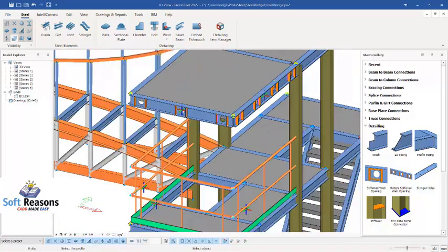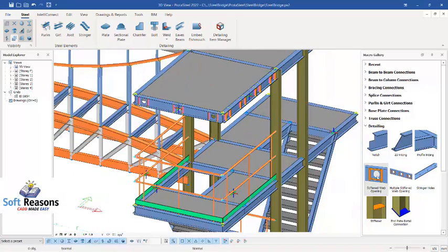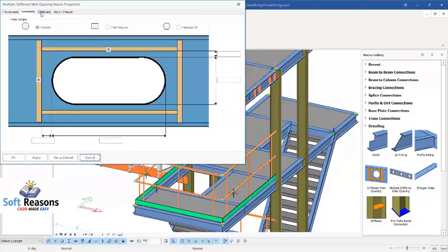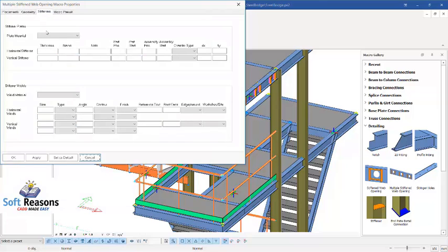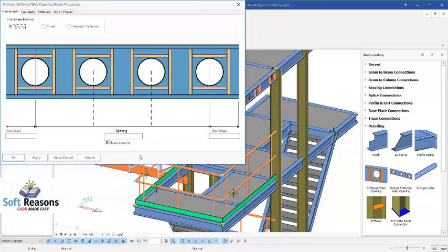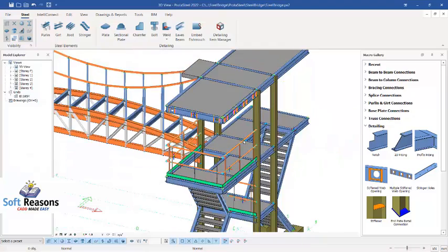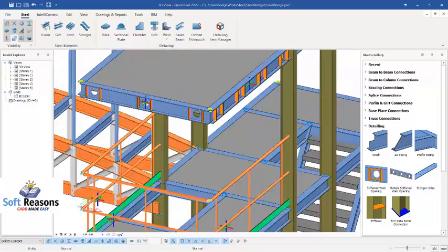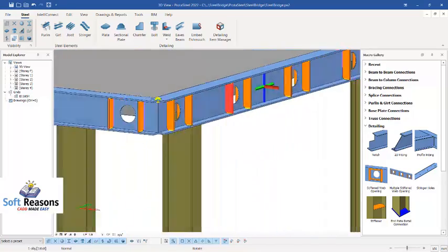Just like this. If you really want it with a stiffener, you just have to right click on these provisions and then you have this. Once you have this, you can look at the placement as well as the geometry, and then the stiffeners. If you really want to have a stiffener plate, you can also make provisions here. After you are done with your settings right here, you click on OK and then proceed. So that is how you can create a castellated steel member just like this.